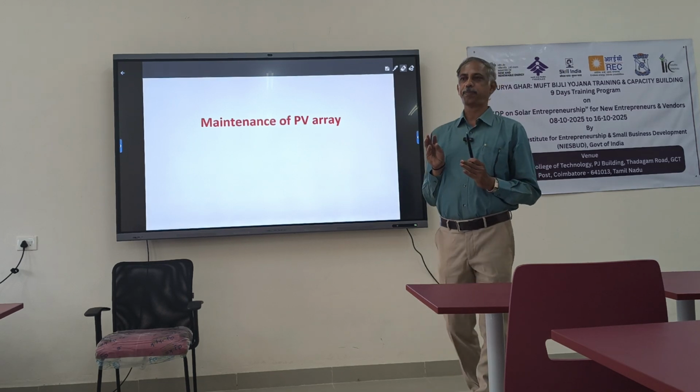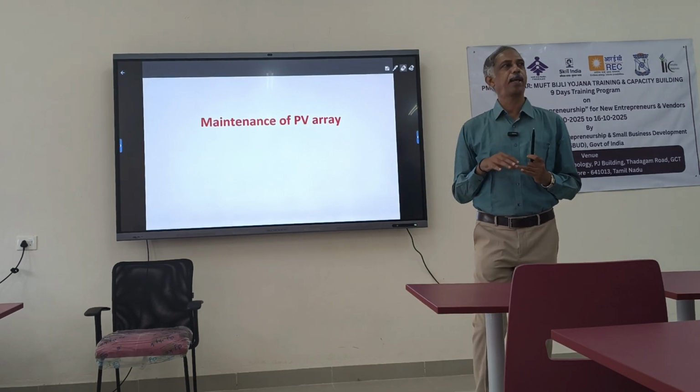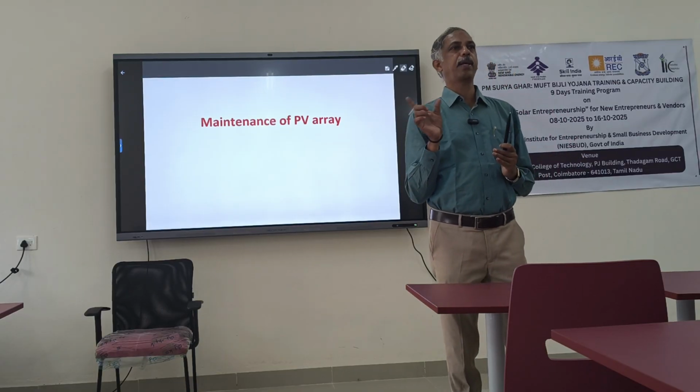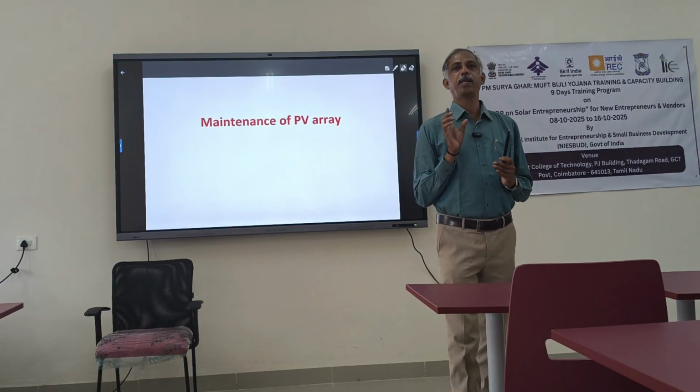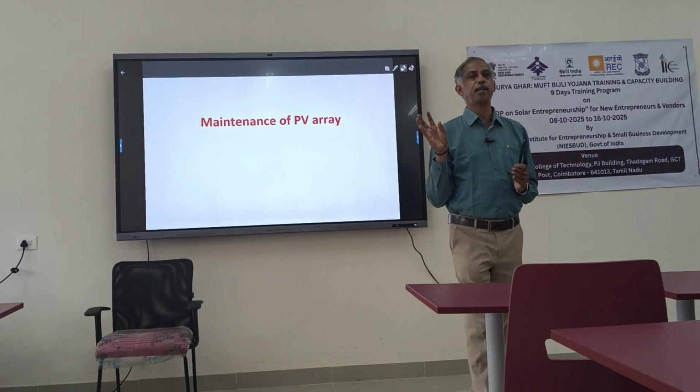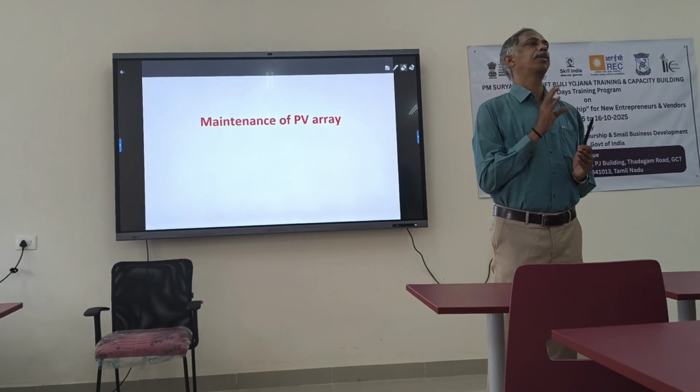It is an interface. We can use a buck converter, boost converter or buck-boost converter. Depending upon the tracking range of resistance, the buck-boost converter is the best suited converter. That converter makes the load impedance variable to the source.